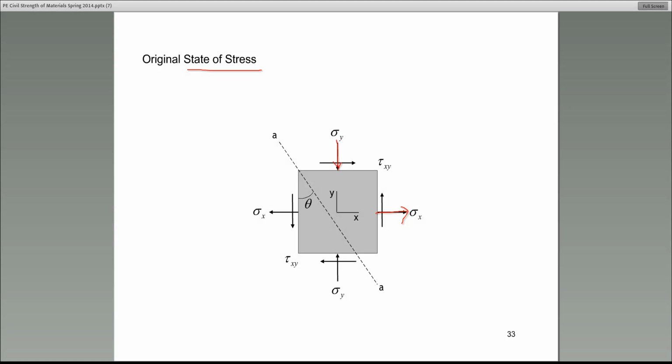All right? What about these other stresses? I'm going to show it in, let's say, blue. This, guys, this is a shear stress. You see that? That's a shear stress. Let me tell you something about shear stresses. These shear stresses are shown acting parallel to the plane. All right? You see that? The red stresses, bending stresses, or axial stresses, they are perpendicular to the plane. The blue ones, those are shear stresses. They are parallel to the plane.